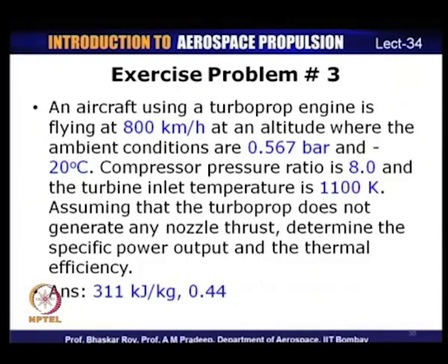So, these are 3 exercise problems for you based on cycle analysis exactly the same way we had discussed in today's tutorial session on 3 different cases: a turbojet engine, turbofan engine and a turboprop engine. And in the second problem, of course, it is a mixed turbofan. So, there is only one nozzle which generates thrust. So, you have to calculate nozzle entry properties determined based on an enthalpy balance between the 2 streams.